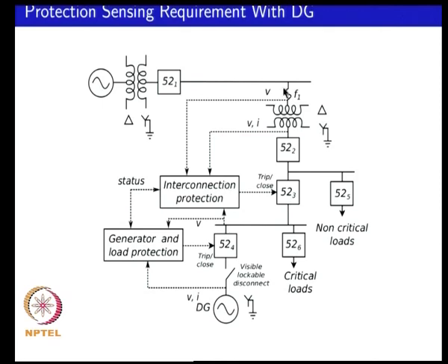For example, over here you might have voltage measurements at the high voltage side, which means that you would need something that measures at the distribution voltage level, whereas over here, if you are measuring the voltage, it would be at the consumption voltage level. So, depending on where you are applying, you would need different types of PTs and CTs, and often in a power system application you would also differentiate between whether a CT is protection grade or relay grade, or whether it is metering grade.